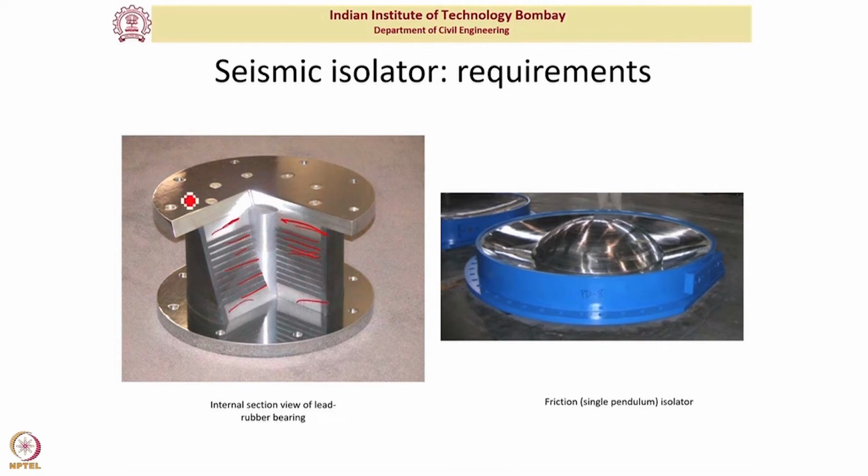And then there is a bolted external bearing plate. Now this bolted external bearing plate is how this is connected to the substructure and superstructure. Okay. These rubber layers are the ones that provide horizontal flexibility. The role of the steel shims here is basically to provide lateral restraint to the rubber, and I'll show you why we need that.